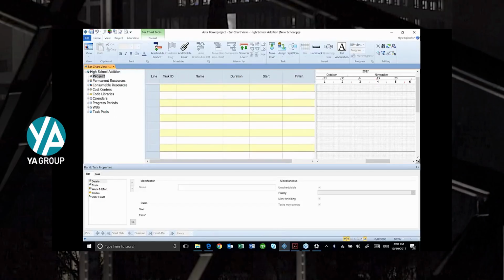That's the first thing I do, on page 15 in your manual, if you downloaded that. I've got a little diagram there, really just to illustrate the importance of doing things in a sequence. I always recommend that the first thing you do when you create a schedule is to go in and set up the calendar so that you have a good foundation. The calendars are what the software uses to calculate days and assign dates to certain activities. A good calendar can really be a very helpful thing, or it can really make things difficult.